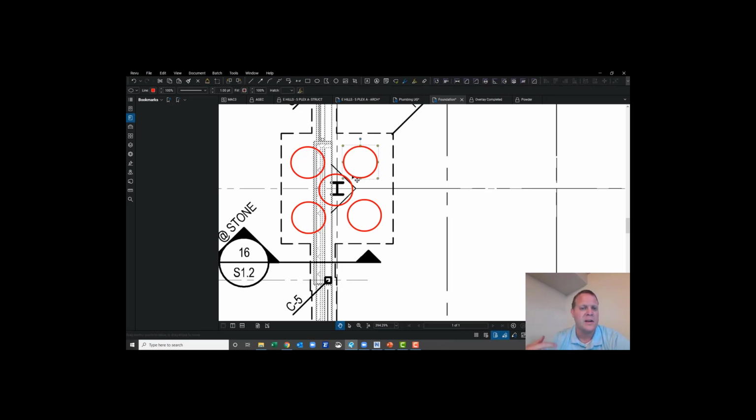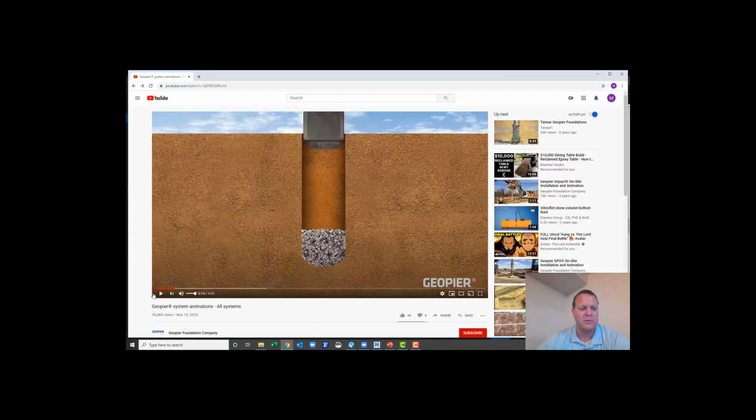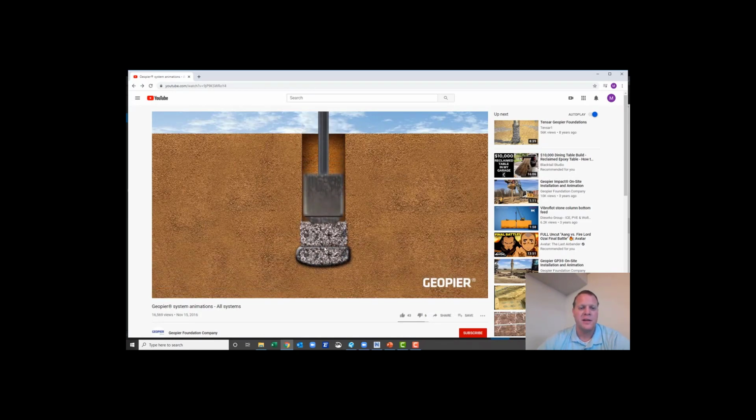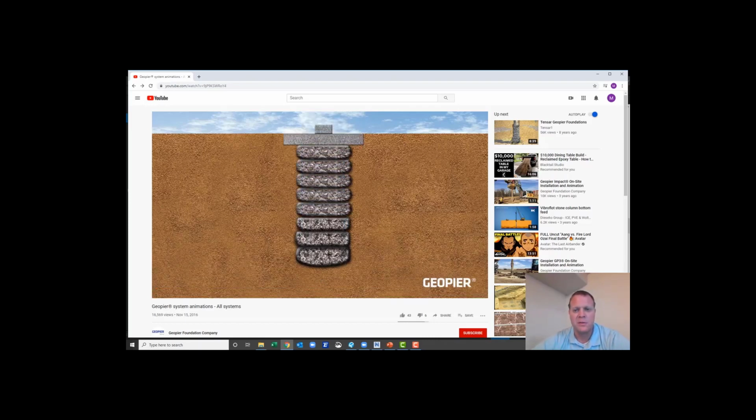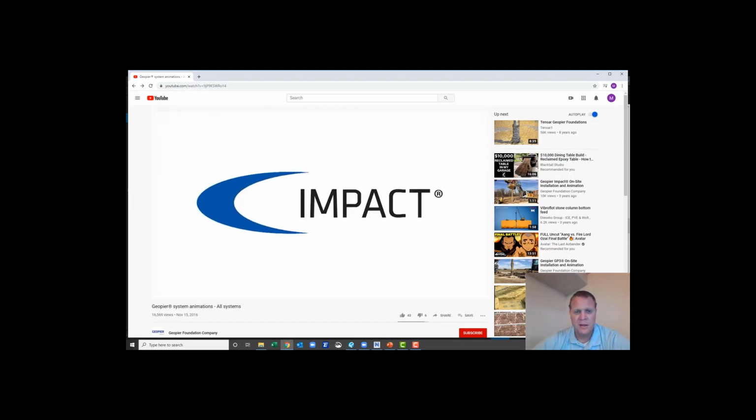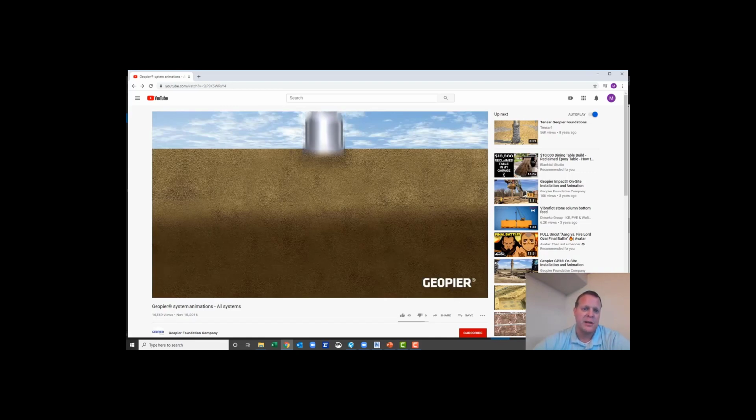So I do want to talk about what I like talking about, the entire assembly, the entire system. Let's look at this. I found this thing on YouTube, just a good example of what a geopier is. So they take a bunch of rock, they put it in a hole, and it's pretty sweet, and they vibrate it down, and it creates these mushroom looking things, and it improves the bearing capacity of the soil. So this was a project near Jordan River, if you know where that is, and it was river bottom type sediments. And this is actually what we had right here, where they vibrate this piece on a track hoe down, and they fill it up with gravel and then vibrate it. That's exactly what we had on our site, something like this, to improve the soil.